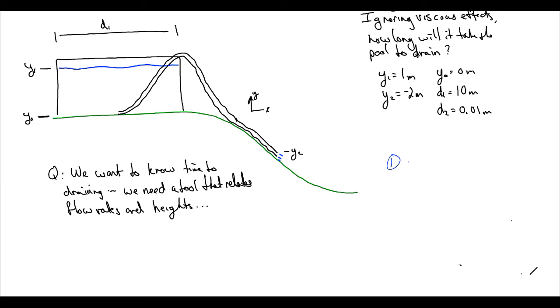Now in practice, the fact that this is equal to a constant everywhere along a streamline means that we can compare 2 points along a streamline, and we know that at those 2 points, this summation has to be equal. Which means that every time you use Bernoulli's, essentially what you're doing is you're drawing a streamline, and you're going to analyze 2 different points on that streamline. So I'm going to pick a streamline. I'm going to start here, and I'm going to pick a streamline here at the exit. So I'm picking a surface, and I'm coming down, and I'm drawing my streamline.